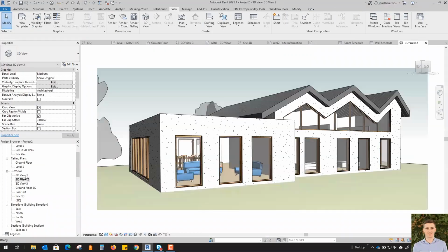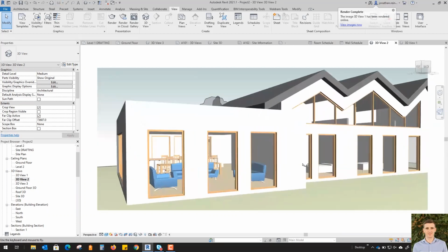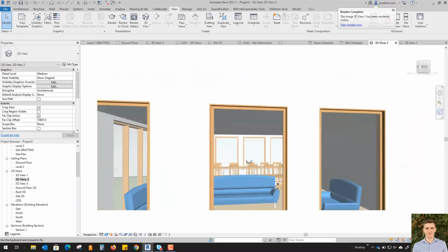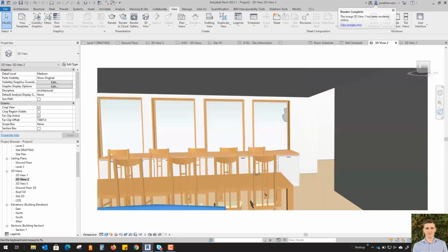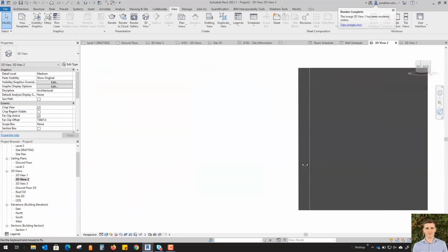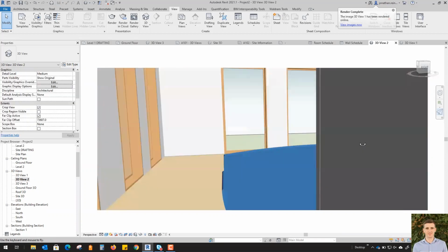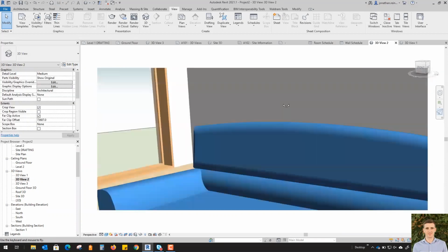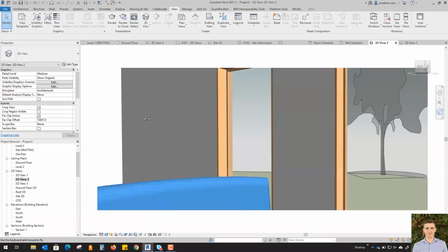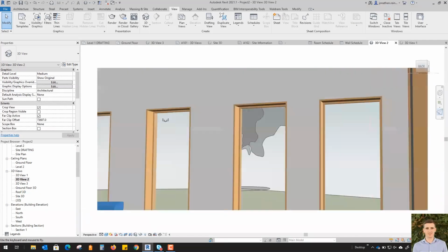While you can create, as we know, rendered images in the product, you can also create rendered fly-throughs as well. But a quicker way, maybe if you're showing a client on screen, is from a 3D view. Added in this latest release of Revit, you can use something called the fly through the building. You can take any 3D view, whether it's realistic, a shaded view, or just a black and white hidden line view, and on the right hand side of the 3D view, use the little paper airplane symbol to move around your building and present it to a client.